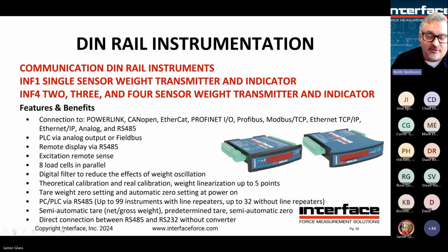And these are all specific. You don't have one model that does POWERLINK, OpenEtherCAT, Profinet. Sometimes there's a tax to be paid to the various vendors who control Profinet or whatever. And so you definitely don't want all of that built into one because it makes the cost go way up. So each one is very specifically either the Profinet one or the Profibus one or the Modbus one, et cetera.